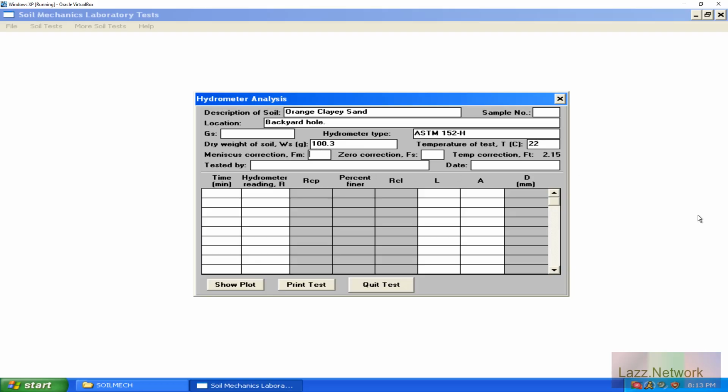Okay, so we got our meniscus correction. This one I'm just going to have to ballpark off the top of my head because I do not have a calibration record of our hydrometer on hand, because that's all at work. Or maybe, did I write it down anywhere? I did not write it down anywhere on any of my notes while I was off, which is all right. Like I said, I was going to ballpark it anyways.